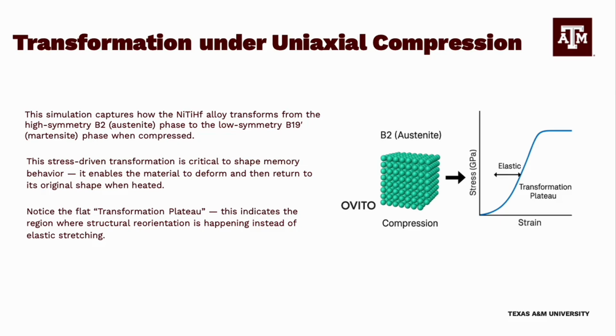This plateau is critically important. It indicates the strain is being accommodated not by elastic stretching, but by the transformation of austenite into martensite.